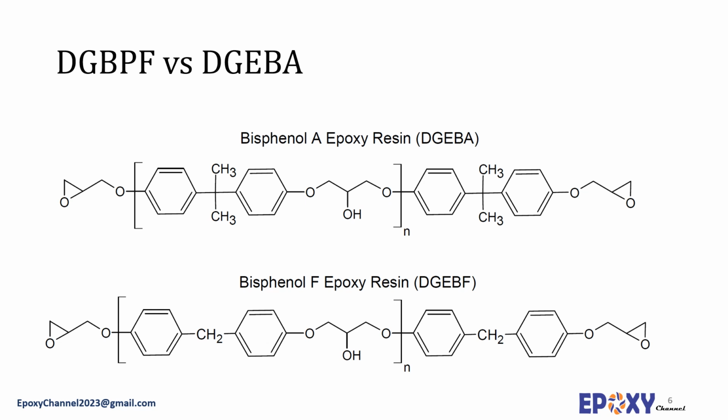There is also a possibility of making bisphenol A and bisphenol F resin blends, as BPF has a good established track record as a crystallization inhibitor for liquid diglycidyl ether, with similar chemical reactivity, and also the chemical structures of both compounds are kind of similar. This way, diglycidyl ether bisphenol A can be modified. Consequently, non-crystallizing liquid epoxy resins, which are blends of diglycidyl ether bisphenol A and diglycidyl ether bisphenol F epoxies, are available. To sum up, to modify diglycidyl ether bisphenol A resins for reducing the viscosity or inhibition of crystallization, diglycidyl ether bisphenol F resins are employed.